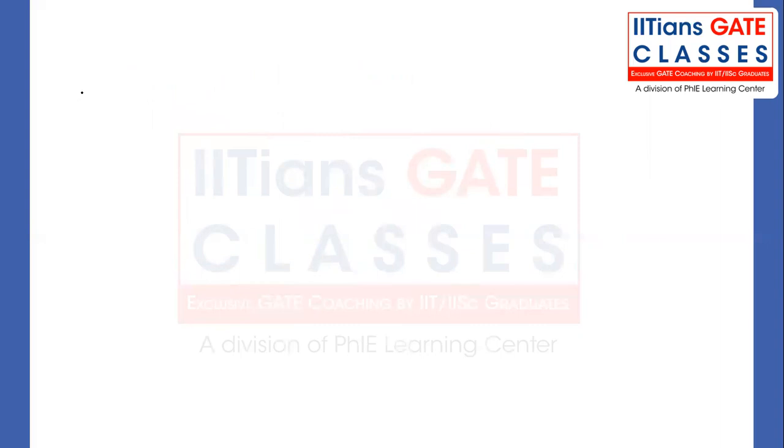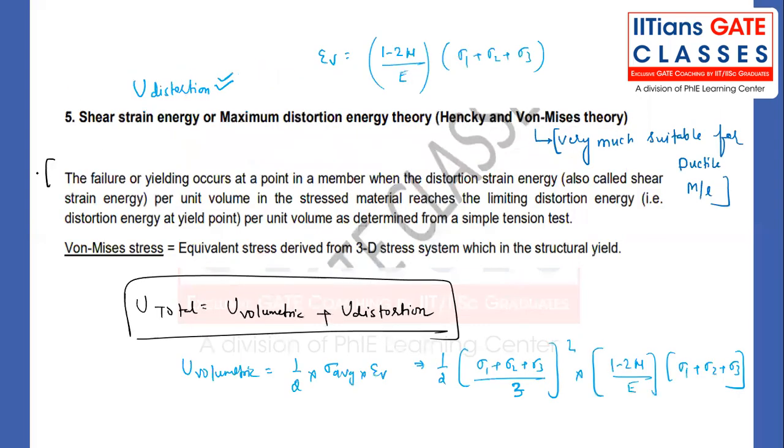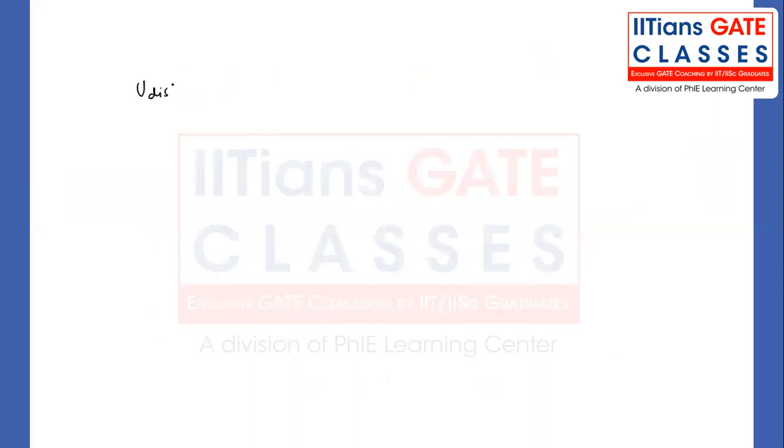So what does this theory say? If you recall this statement, the failure will happen. Read this statement: failure or yielding occurs at a point in a member when the distortion strain energy, also called shear strain energy per unit volume in a stressed material, reaches the limiting distortion energy, that is, the distortion energy at the yield point. We say the failure will happen. That means if the total distortion energy is less than or equal to the distortion energy at the yield point, we say the material is safe. If it is more, we say the material has failed.